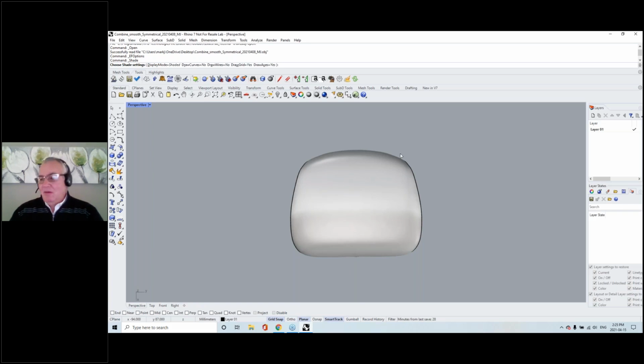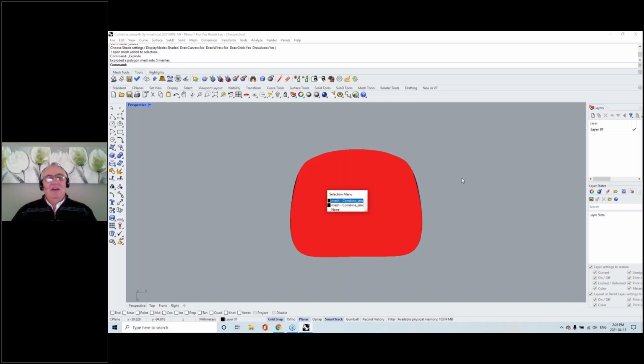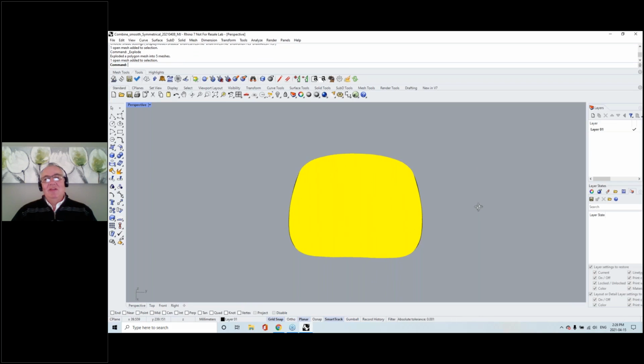So the first thing I'm going to do, because this is a single file, as Peter had mentioned, he joined everything, is explode that into those 5 patches. What I do over here, I have my explode icon, or I can actually type explode up here, but I'll just use this. And now, if I look, I will have separate patches for all these pieces.